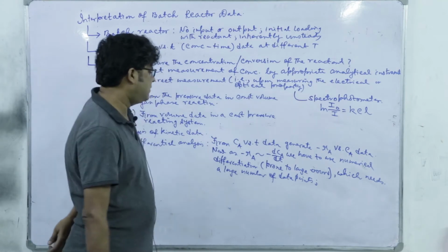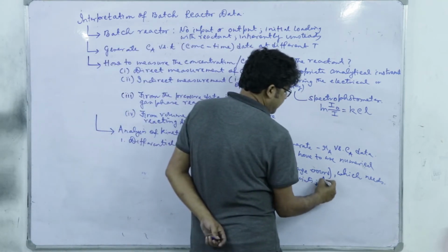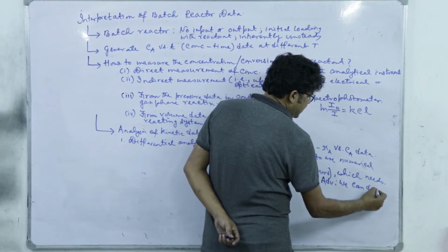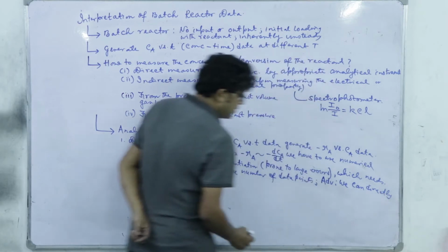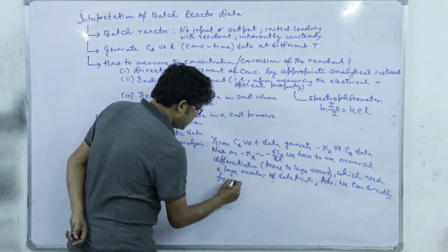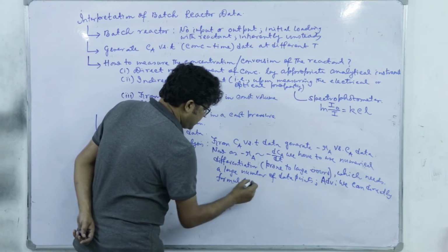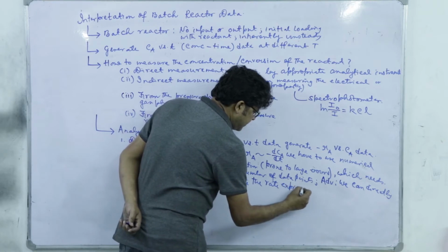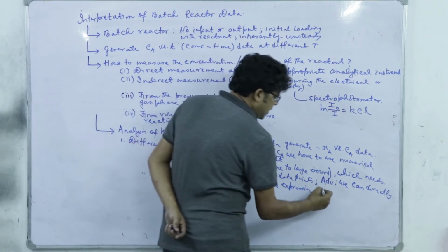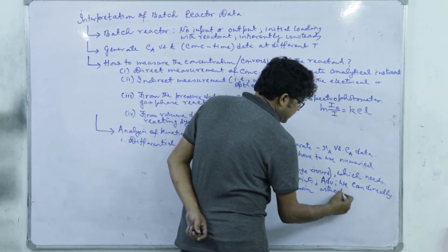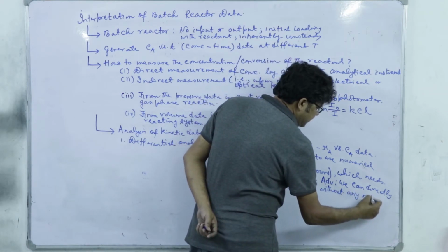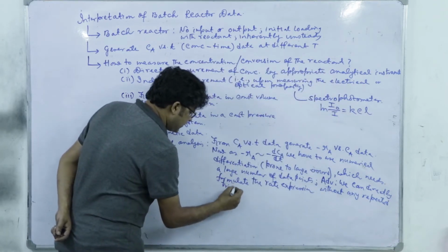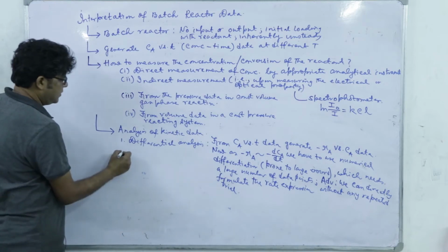However, what is the advantage? We can directly formulate the rate equation or rate expression without any repeated trial, right, which is the typical characteristic of the second method, that is the integral analysis.